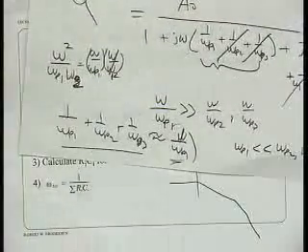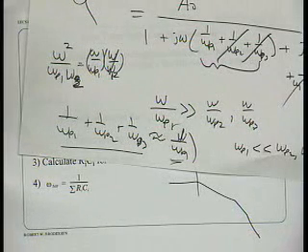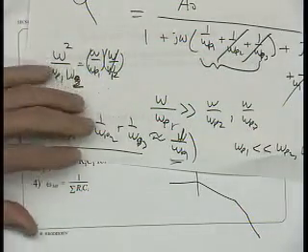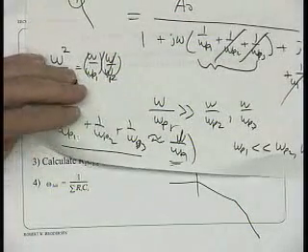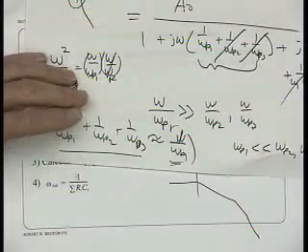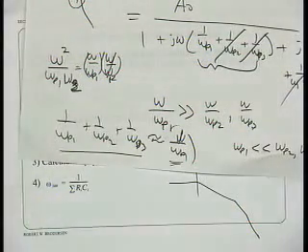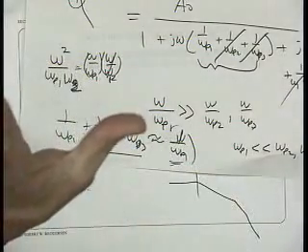So the answer is, well, why do all this stuff? Why calculate all these extra things? Why not just go for the one that's the biggest? The question is, which one is it? How do you figure out which is the most important one? And that's what's not so easy to figure out. This is a way so you don't have to think, right? The strategy is, I can do something and figure out the lowest frequency pole and just go through this little calculation, and I'll calculate the lowest frequency pole.